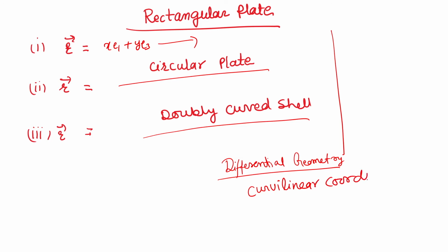So, it is slightly different. But our aim is not to explore wholly the curvilinear coordinate system. Our aim is just the basic theorems required for developing the shell theories. In that direction, I first defined the curvilinear parameters and the first fundamental form of surfaces, the second fundamental form of surfaces, and various theorems like Rodrigues theorem, Weingarten theorems, Gauss-Codazzi equations.